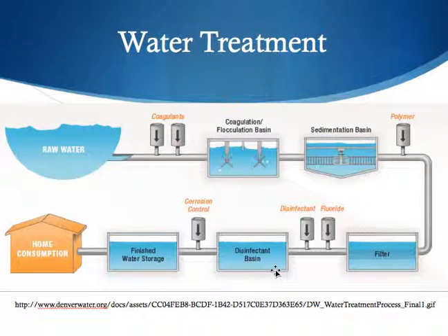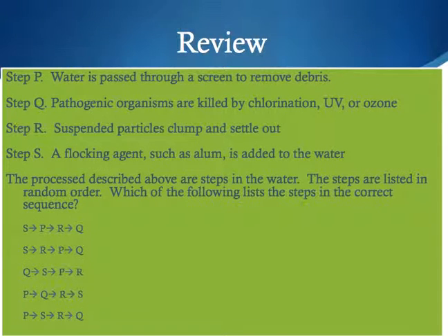And then it's going to go to a disinfection chamber, and we're going to do chlorine. We can do chlorine, ozone, or UV lights here. We're going to add fluoride at some point. And then we're going to store it. And we may need some sort of corrosion control involved in that process. So fairly straightforward, a little bit different than our wastewater treatment plant.